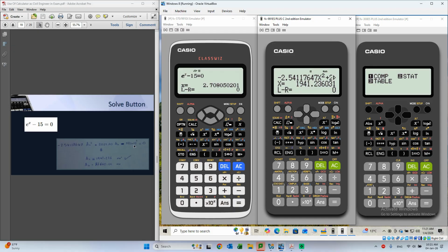Let's say this is for RC, reinforced concrete. We're designing a beam, and we're expecting the reinforcement to be close to, say, 1,000, 2,000, 3,000 millimeters square for the area of the steel. So when I'm solving here, shift solve, the first number that I'm inputting is important. I can just type 1,000, since I'm expecting 1,000, and it gets the answer for me.